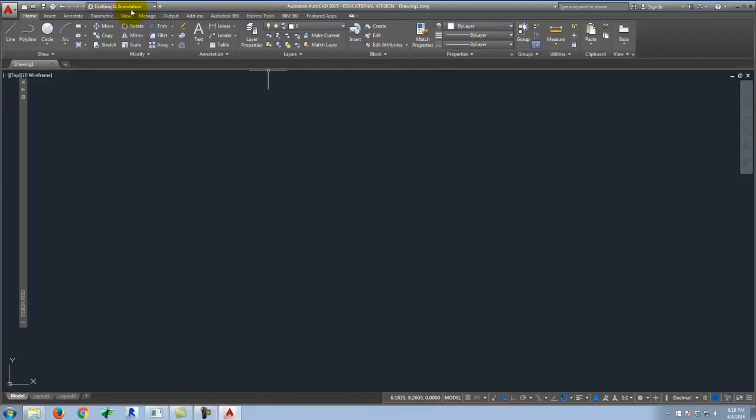If you're missing this little menu to be able to even select drafting and annotation mode, if you click the little triangle at the end of the row here, you can choose what you're seeing. If you don't have workspace checked, it would look like this, and then you can't pick it. So we'll go ahead and check workspace, and then you can see drafting and annotation. I apologize. Again, a fresh restart would have been a smart move on all our parts. But I don't want to have everybody do that because then we'd sit here for 10 minutes while the computers booted back up. Okay, so below that we have what AutoCAD calls its ribbon.